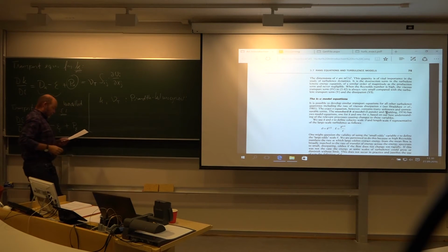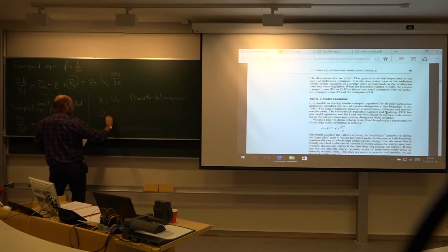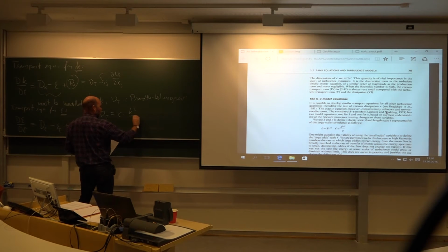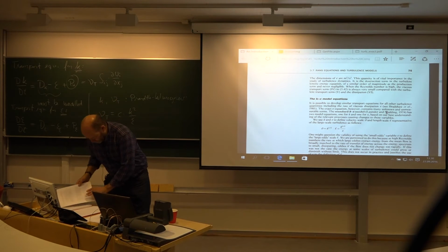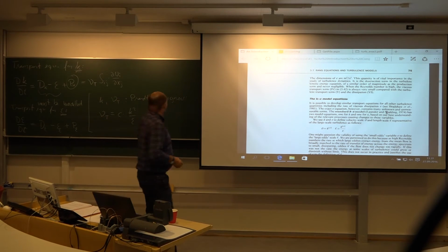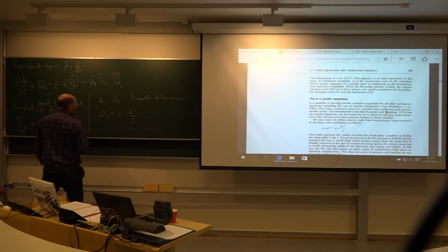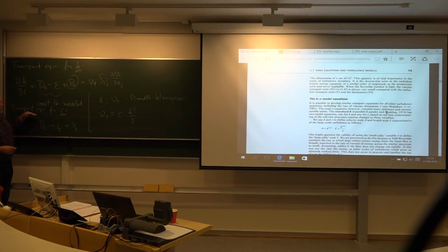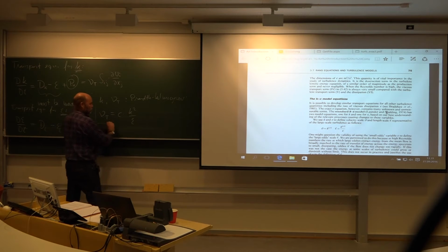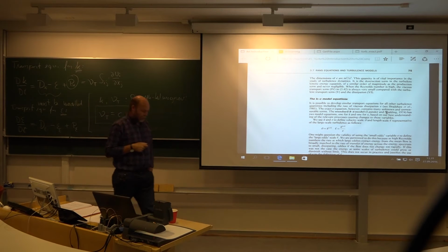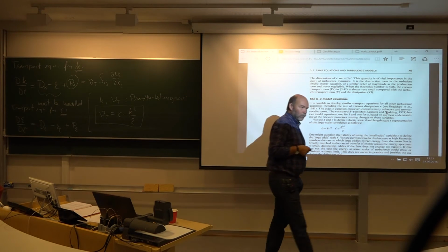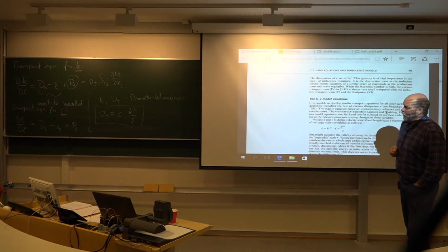Also based on dimensional analysis, you find that eddy viscosity is given by a constant multiplied with K squared over epsilon. For short. And then we're done. Then we have two transport equations, for K and for epsilon. And we have one algebraic equation giving us the eddy viscosity that is entering into the Navier-Stokes. So now we have a closure of all the equations. But.